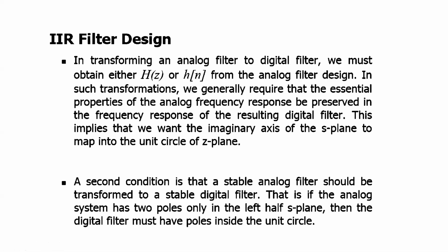In IIR filter design, if you remember the comparison that I was showing between FIR filters and IIR filters, for given specifications, FIR filters will always take a high order. Let us say if you are given some specification, and you choose an FIR strategy to implement it, you may require the order of the filter to be 40.